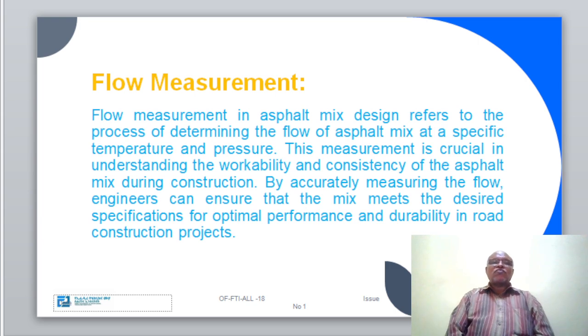Flow, also known as flow value or flow index, is a measure of the deformation of asphalt mix during compaction. It is determined by measuring the deformation of the sample under a specified load and temperature condition. A higher flow value indicates greater workability and ease of compaction.